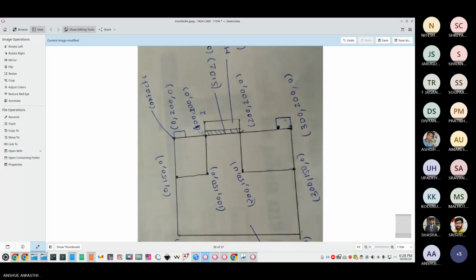Similarly, the drain total contact is 50 nanometers, and it is ending at 300. So 50 nanometers before 300 will be 250. So it will start from 250 and go to 300. The source goes from 0 to 50, the drain from 250 to 300, and this thickness is 2 nanometers, that is from 200 to 202.